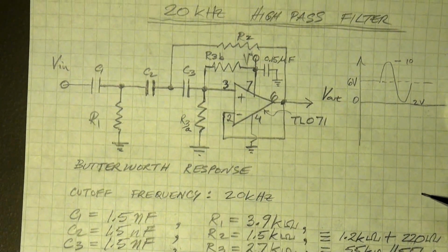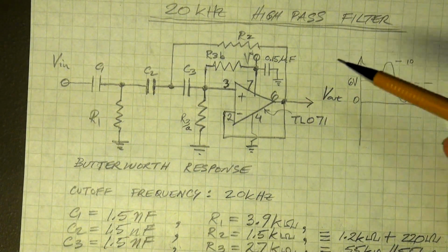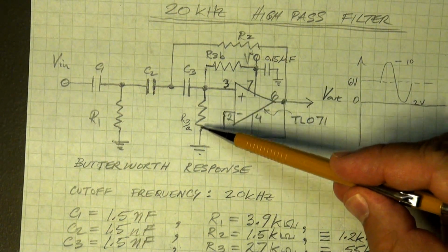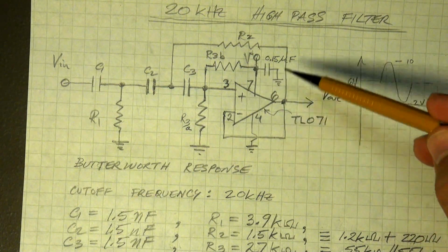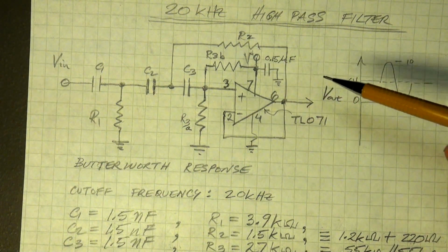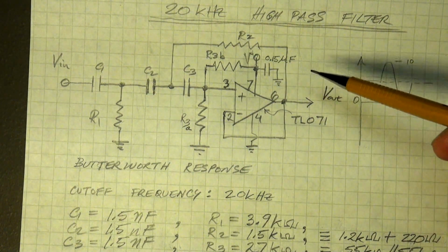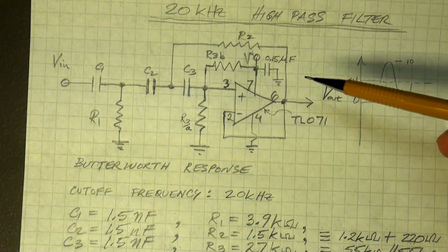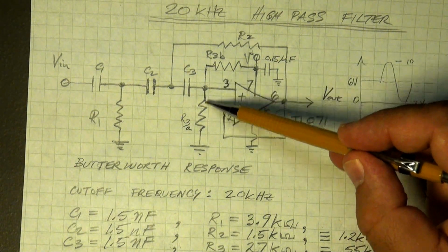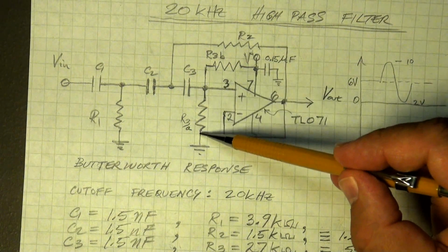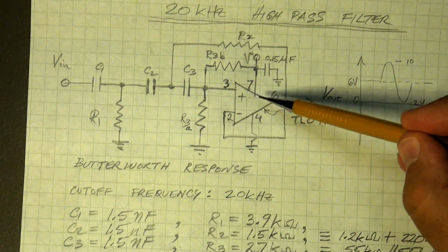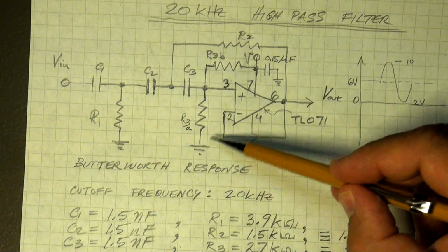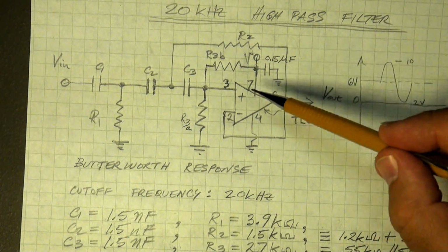So if connecting either resistor either to ground or to V plus, from a DC or AC analysis point of view, it amounts to the same thing. It is as if both are in parallel connected to a constant voltage, either ground or V plus. They act in parallel.